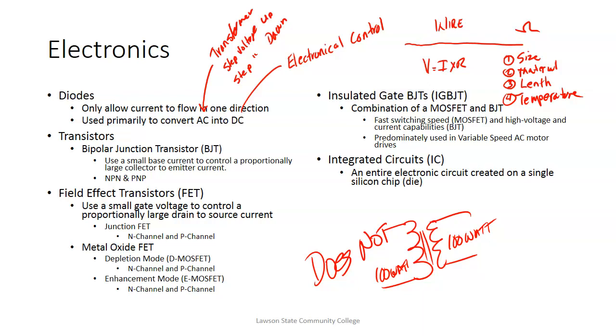So just very, very small resistance can drop a lot of voltage over distance, and that's why your battery cables have to be really, really good, and you keep those connections up there on the battery real good. And one of my sisters-in-law, her starter wouldn't work. It'd work every once in a while, and the battery connections were fine, but she had a loose connection on her starter. So just that 1 ohm or so resistance on that loose connection, it wasn't her battery, it was her connection on her starter that was actually bad.